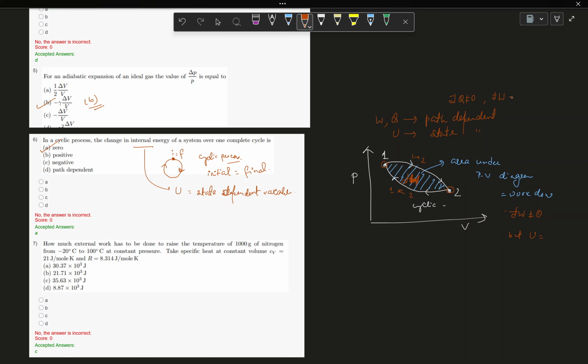So this extra cut sign in the d sets apart these two variables from the normal variable like U, because these are path dependent. But dU we do not write with the cross, we just write dU because this is state dependent. Okay, so this is a sign to separately identify which quantity is path dependent and which is state dependent.